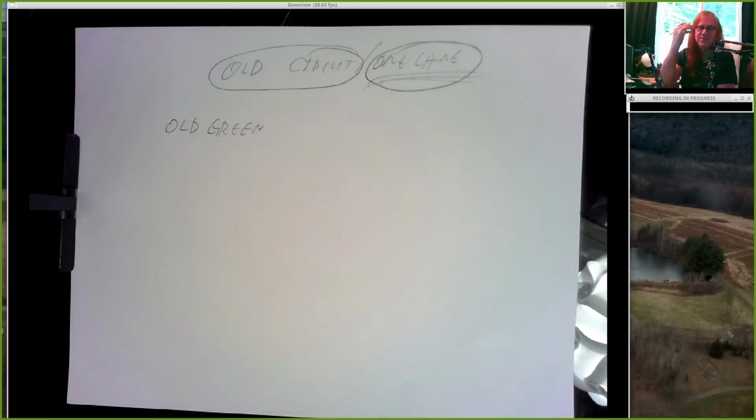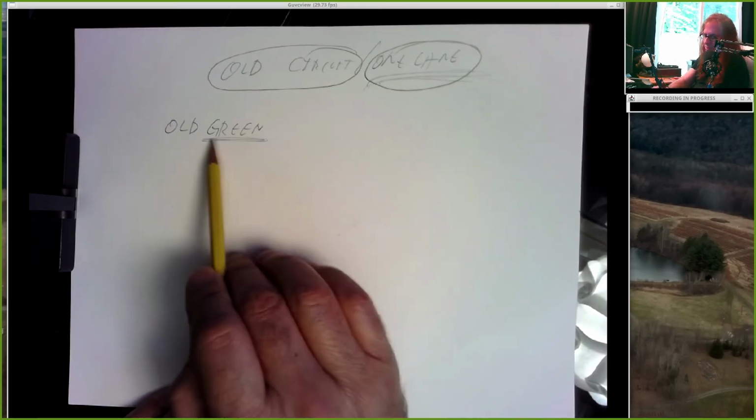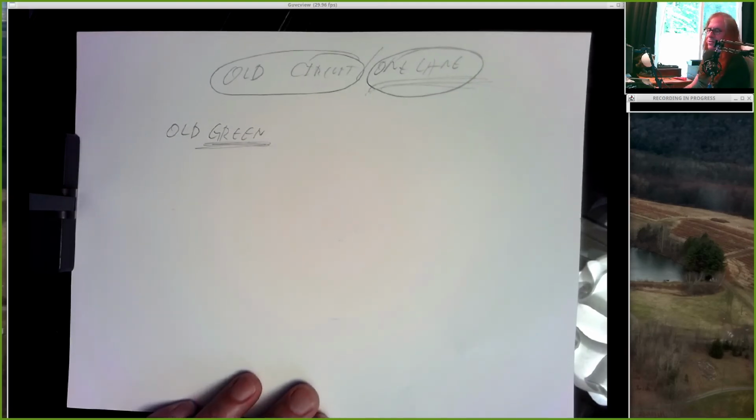So, we made a truth table with car sensors, and we gave priority to one lane, and we wrote equations and minimized them with K-maps and so on. And ultimately, the output of your earlier lab was, you had 3 car sensors coming in, and you could generate a green signal to each of the 3 lanes.